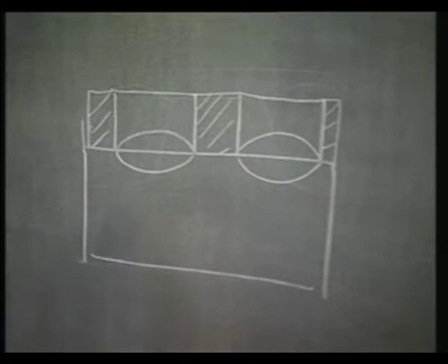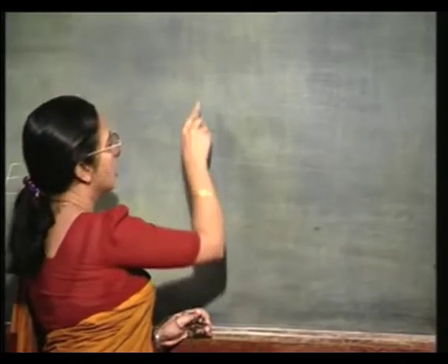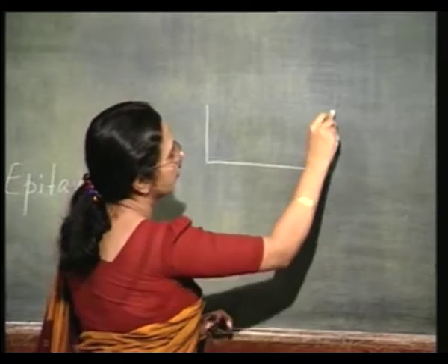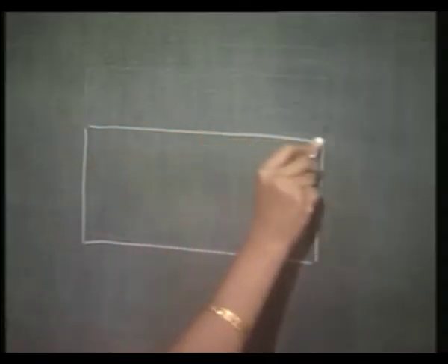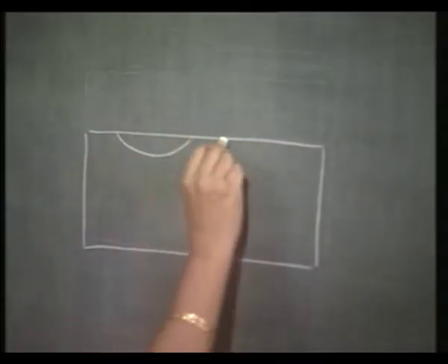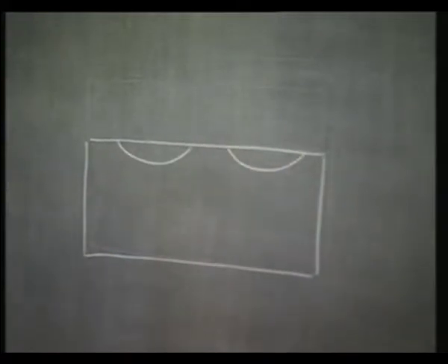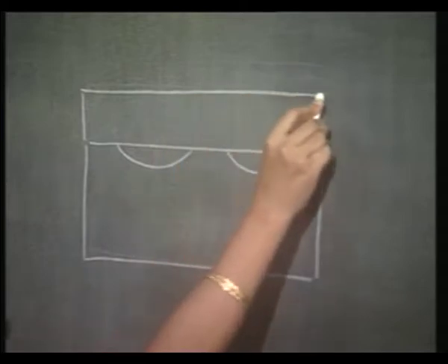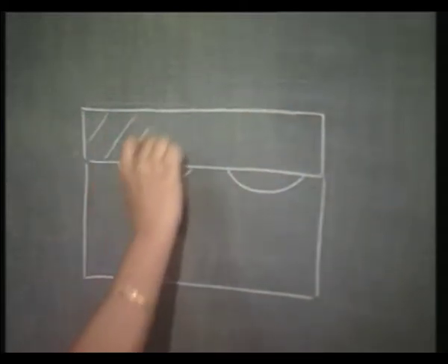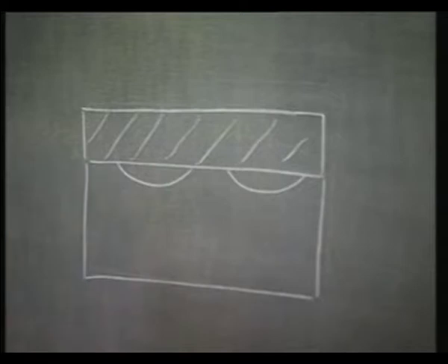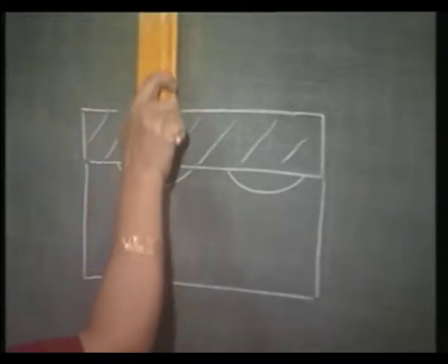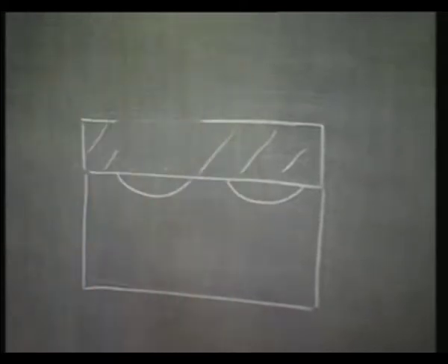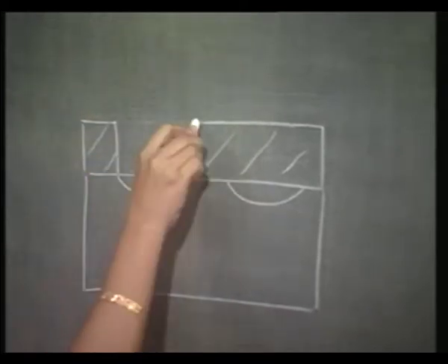So, how do we go about it? We start off by having the p-type substrate and the buried layers. Okay. Then we grow or deposit a thick layer of oxide. We etch the oxide in certain regions aligned with the buried layer.